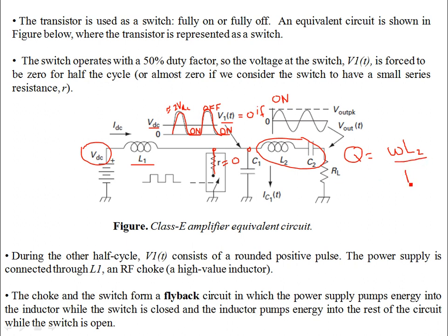Now, suppose this is greater than or equal to, let's say, 10, a very high Q value, so that you have a perfect sine wave. Whatever the resonance frequency is, it will set the output to a single frequency or tone. So without any compromise in the amplitude, we can have a nice looking sinusoidal pattern, with a frequency and the same amplitude for all time.